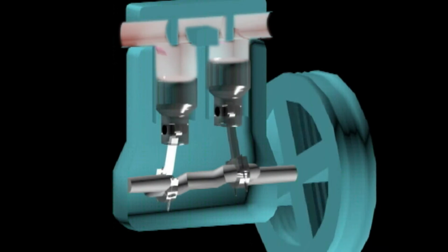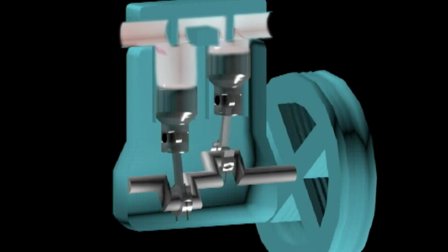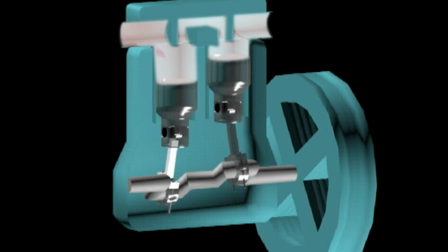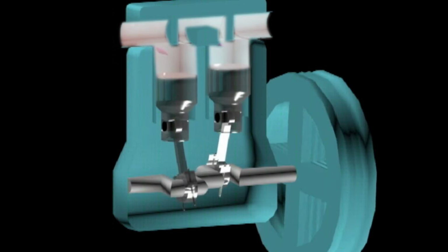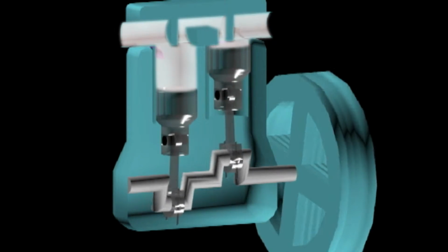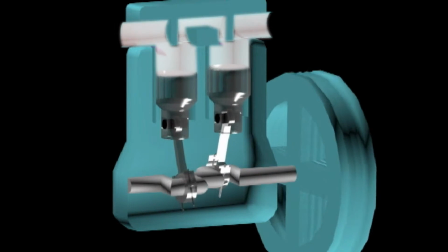On the suction stroke, where a piston is moving downward, the clearance space between the piston and the cylinder head will expand. The drop of the pressure will open the plate-type suction valve and forces the refrigerant to enter the chamber until such time as the suction valve recedes.